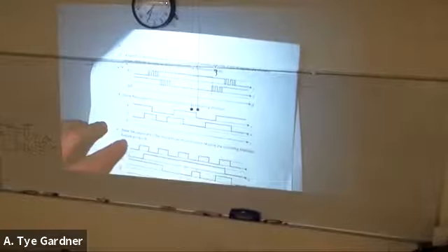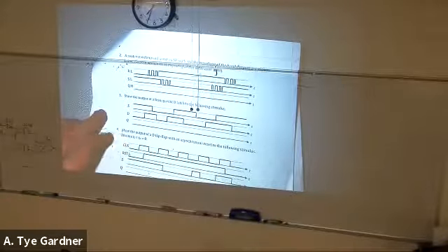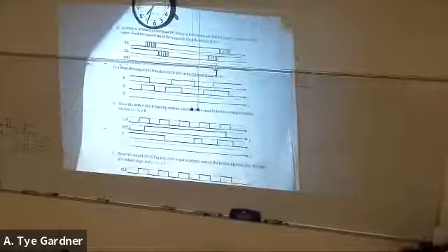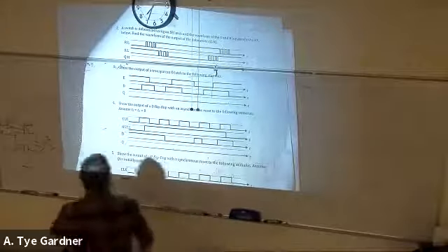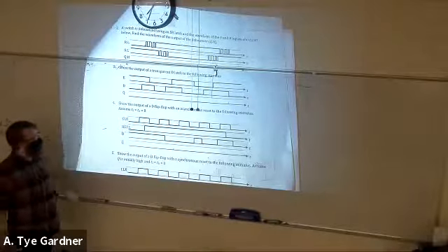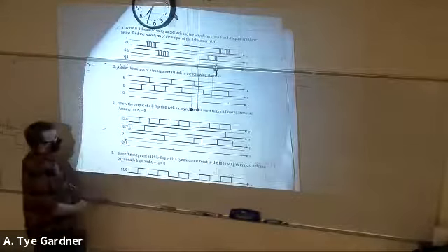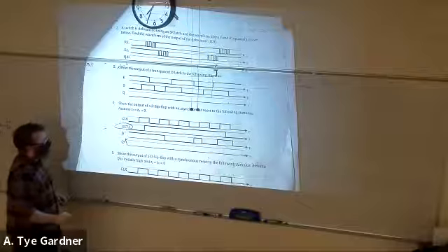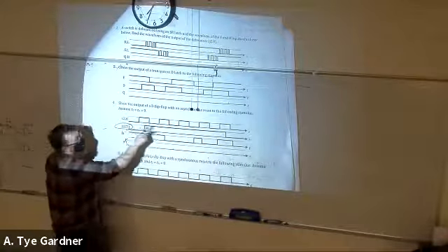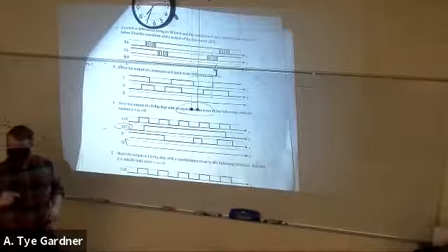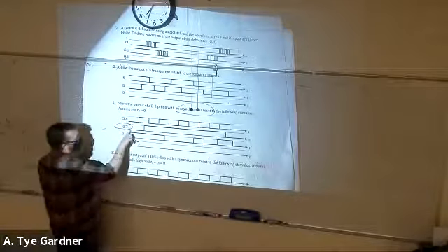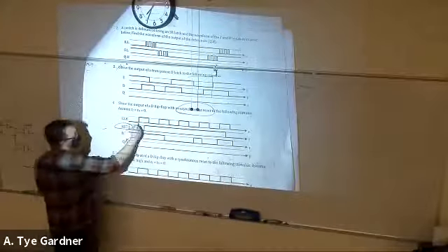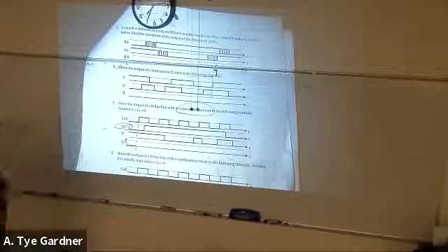So this one is a D flip-flop with asynchronous reset and the following stimulus where we don't worry about setup and hold times. Number 4. This one does not give us an initial cue. Reset is low, active low reset. Since we have an asynchronous reset, it happens immediately. So we know that because reset is low, we're 0, and then we want to identify all of the spots that it might change.